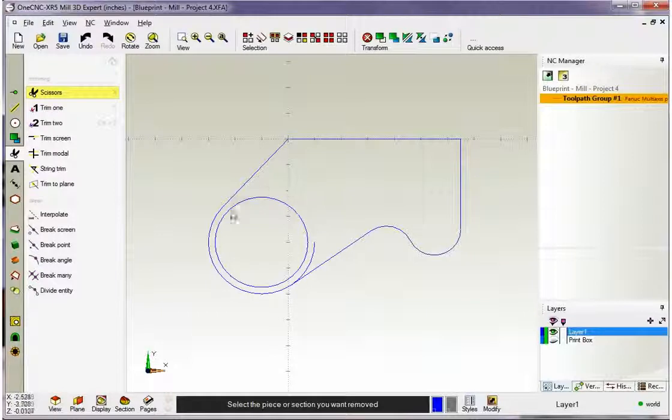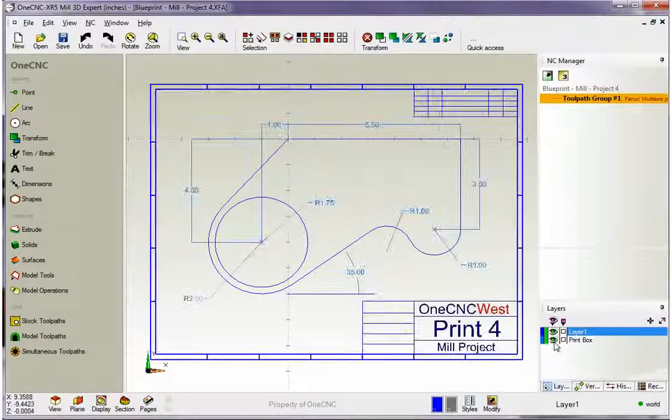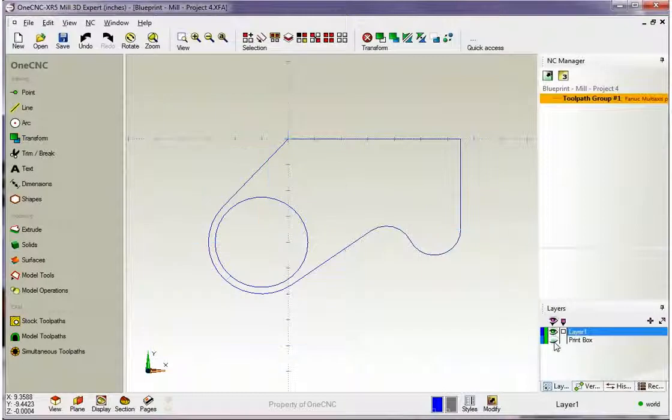Also, don't forget that when you create circles, you have that 0 gap at 3 o'clock, and that's because arcs are created at 3 o'clock. They go all the way around counterclockwise and they terminate at 3. So that's what you're seeing there. So simply just left-hand click on that guy to get rid of him, and there's our completed shape. I'm going to hit the home button, zoom in on that, and let's turn our print layer back on, and that looks like a great shape.